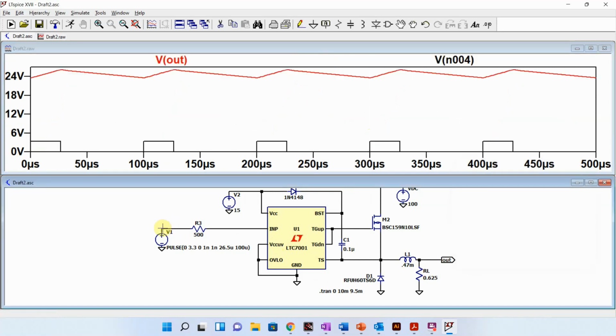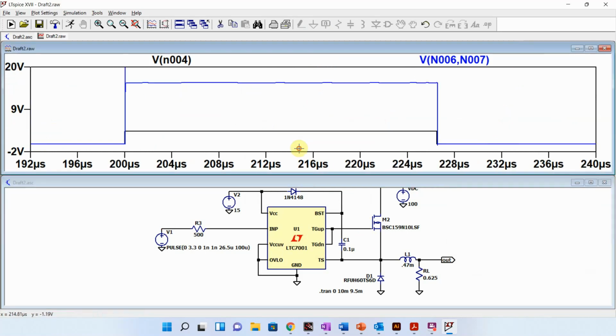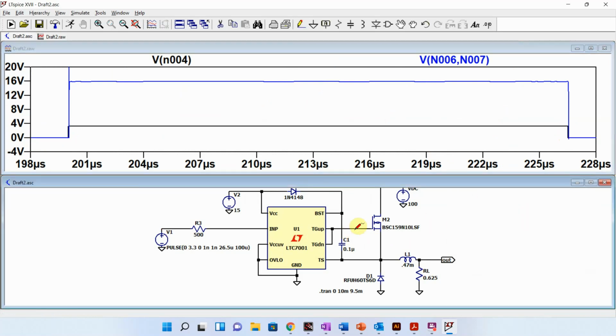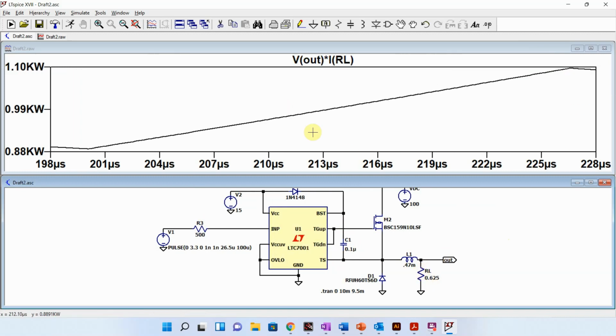And so now if I look at this voltage compared to this voltage, you can see that that works pretty good. So you can see that switching really well. And you see it's taking this and it's converting it up to the 120 to take this 15 and do the bootstrap. So this is actually doing the bootstrap circuit for you, but being able to put out the high gate driver piece.